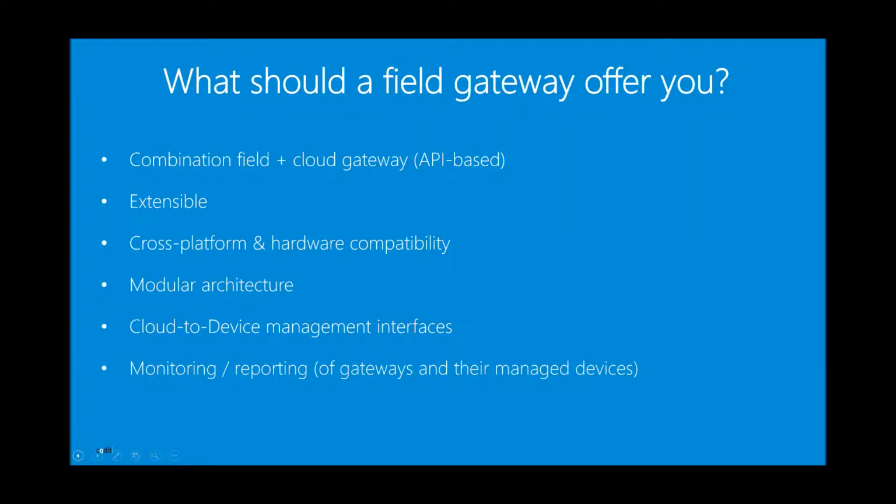The third point is that it's really important that you find a gateway that offers you cross-platform compatibility, but that also allows you some flexibility in which type of hardware this is going to run. So you don't want to lock yourself down to this thing only runs on Linux, this thing only runs on Windows, or what have you. You want flexibility in which operating systems and which type of hardware the field gateway supports, so that no matter the scenario, whether you need an embedded microcontroller and put a gateway there, or you need it on a more capable server, you will be able to run the same field gateway.